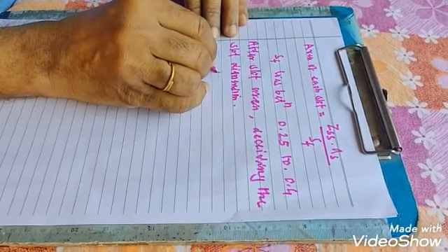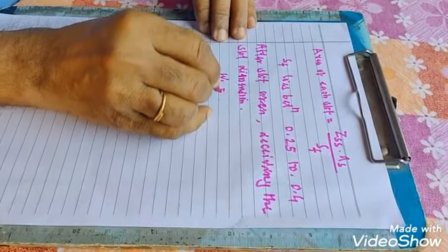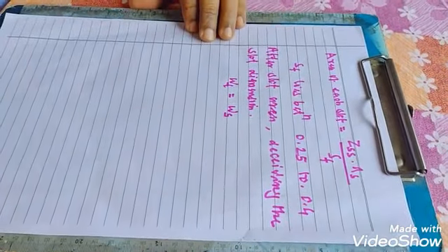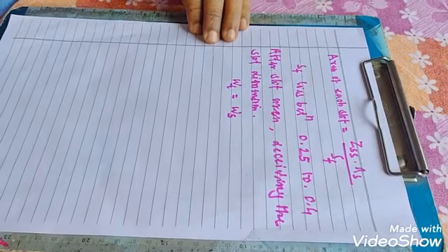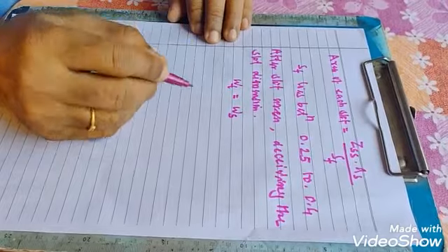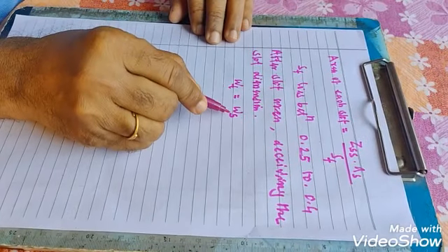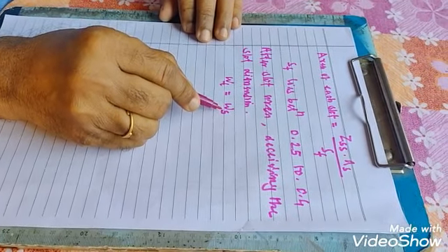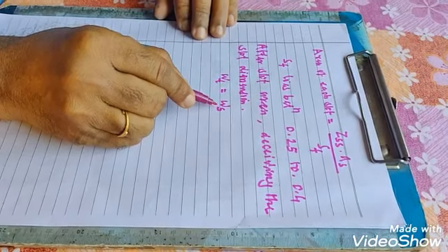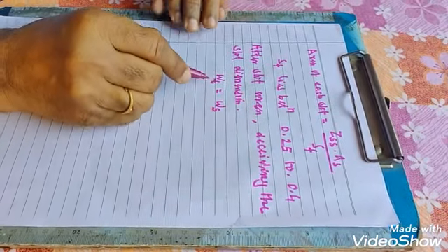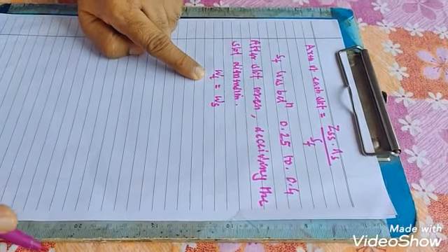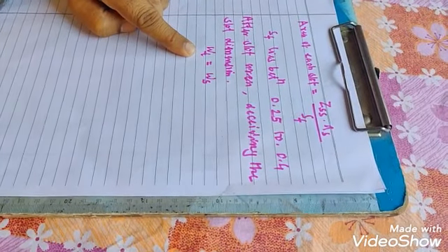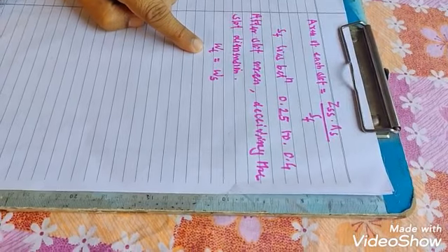Generally, the width of teeth is taken equal to the width of slot WS. Slot should not be too wide. If we make the slot too wide, WS will be more for the same slot pitch YS. If WS is more, then WT will decrease. Width of teeth will decrease so that teeth will become thin. So slot should not be too wide.